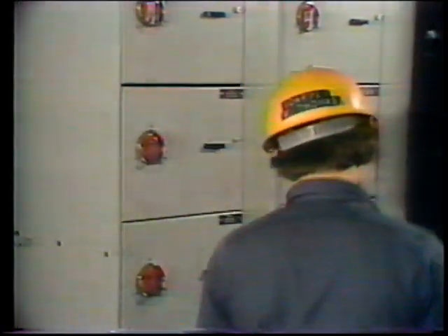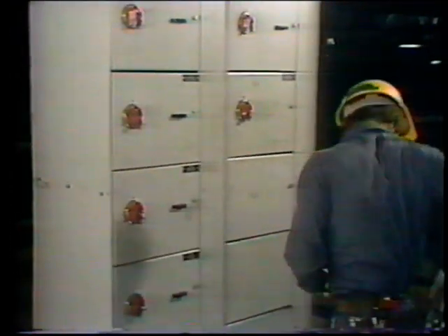Well, that only leaves the power supply to the controller and the fuses. If a fuse were blown, the power couldn't flow through the controller. The motor would not start and both indicating lights would be affected. If power were not reaching the controller at all, these same symptoms would occur. It appears likely that a blown fuse or a lack of power is causing the malfunction. The electrician will have to check the fuses, and by checking the fuses, he will also be checking the available power to the controller. The electrician uses a screwdriver to open the controller cabinet.